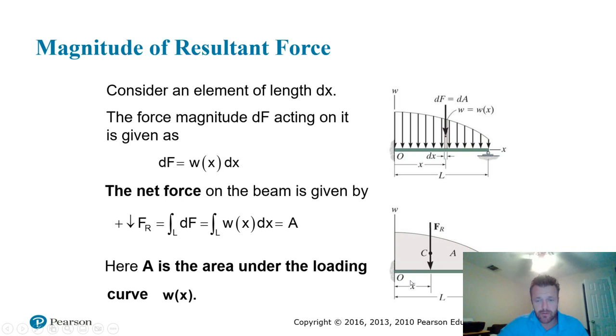But basically what we're going to do is choose in the next slide where to place this force. And since it's a one-dimensional problem, all that I basically have to choose is how far I need to put it away from the origin. So going back to our viewpoint of forces, it's causing translation and causing rotation. Here, when we find the aggregate or the resultant force by integration, what we found is the component of this load that's actually going to induce translation.